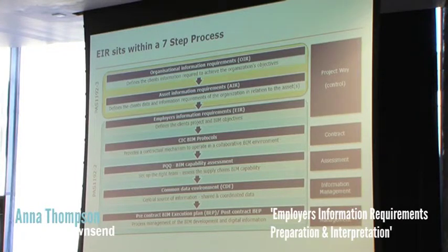And these three documents here, EIR, CIC BIM Protocols, Capability Assessment, go out at the beginning of the project to anyone tendering for work. So the EIR needs to be in place at the start of the project before any tendering or appointment activities start. The client is responsible for putting that EIR in place and including this in his tender documents. So it forms part of the tender documentation.